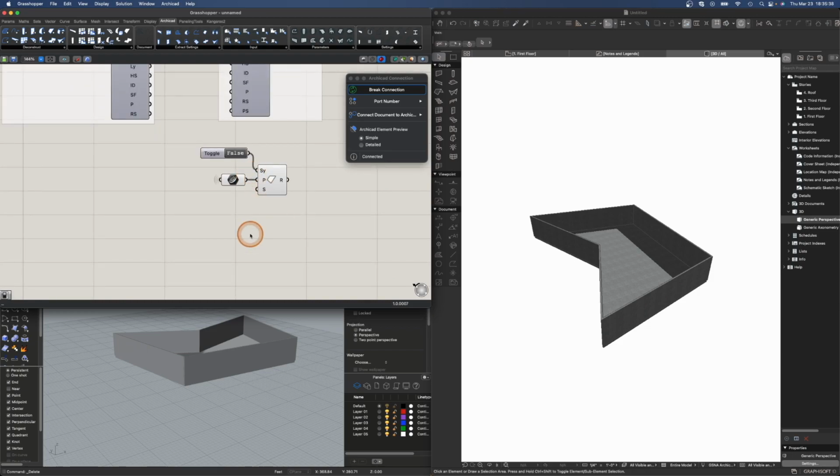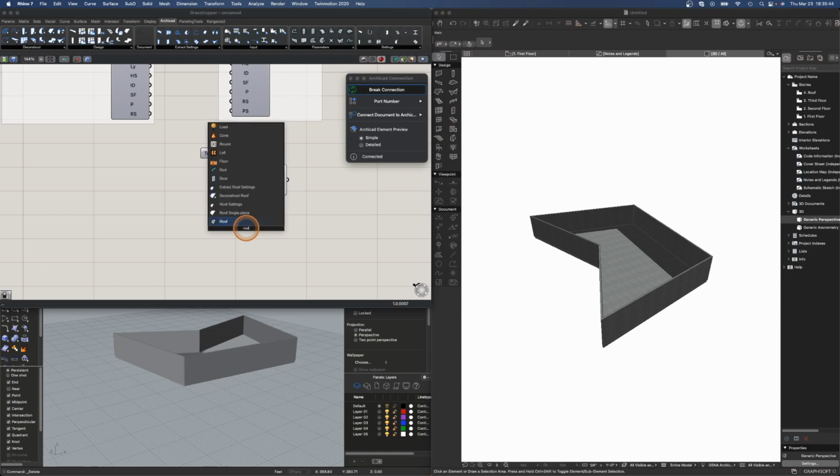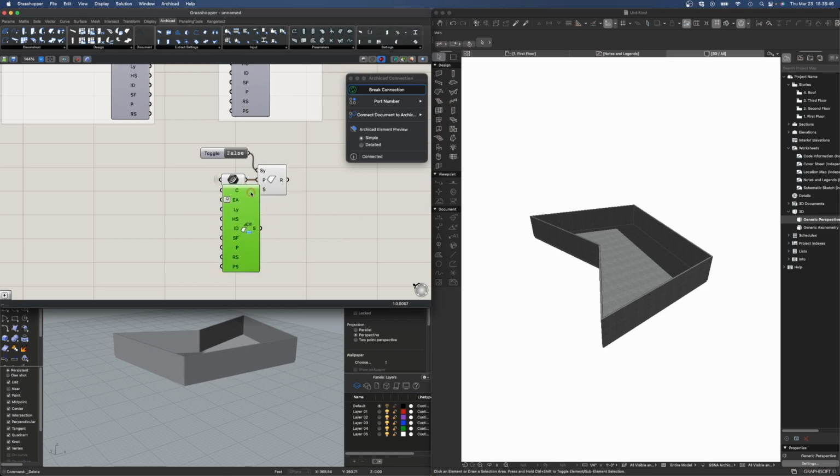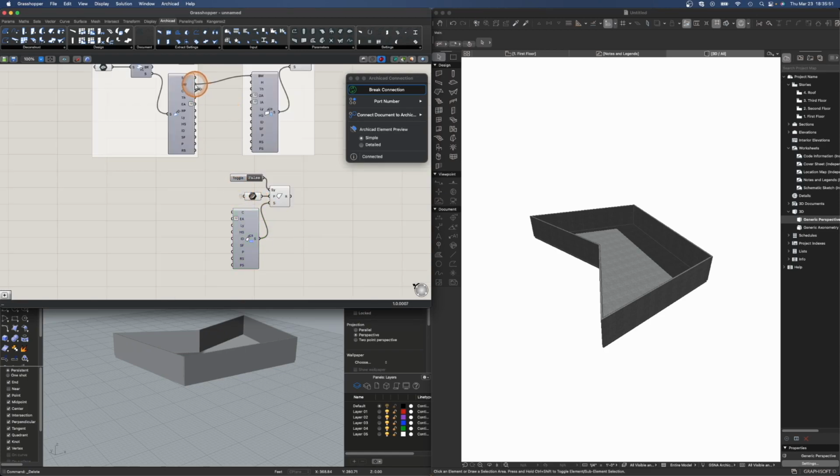let's say I want to make it the same material as everything else. So I will add the roof settings here, connect it to the same building material. Of course, I have to make sure that the structure is the same, which would be basic. Here I will have to get a little tricky actually, because when I turn this on, the roof shows up in the same plane as my base slab.